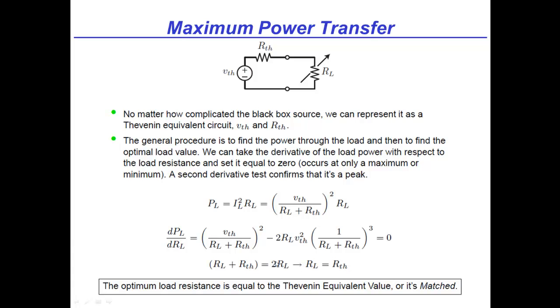That could also approximately be true if RL was infinity, right? Because if RL was infinity, 2 times infinity is still infinity, and you'd say the left-hand side is approximately equal to the right-hand side. But as RL goes to infinity, what happens to the current through your thing? We get to the minimum power transfer. There you go. So this condition therefore necessarily represents the maximum power transfer.